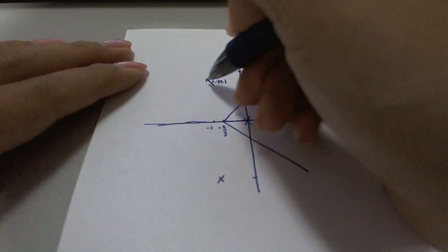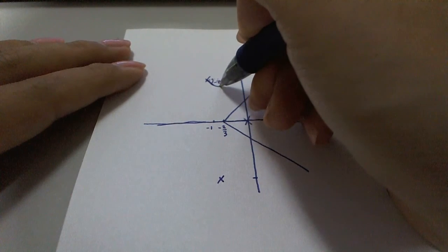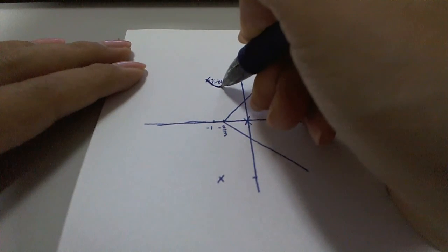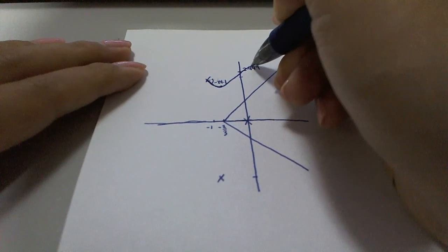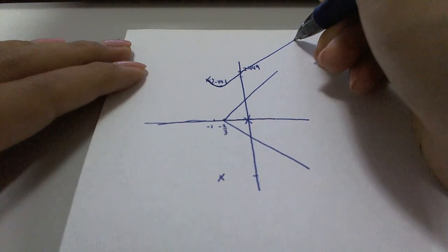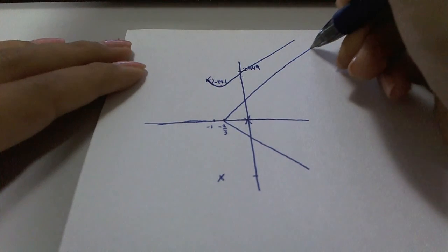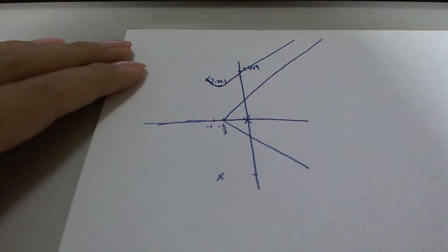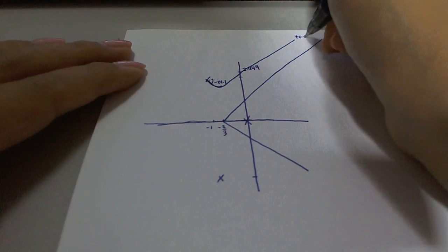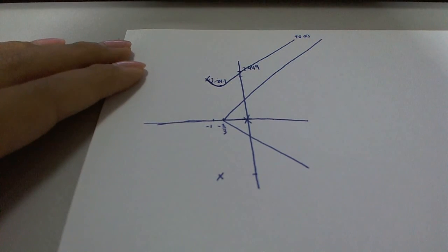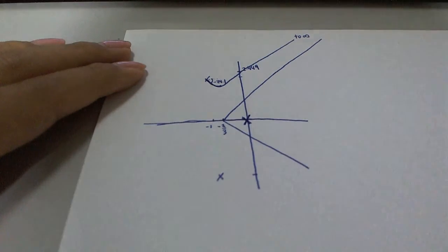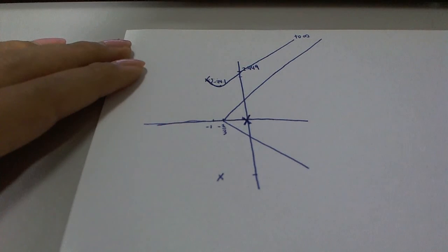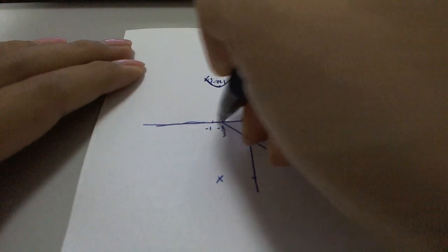The first one is from the first starting point, go down at minus 24.1, and then intersect the imaginary axis, and then it will go to infinity following the asymptote. And then the second one, we have this pole on the real axis, and in this case it will just go to infinity along the real axis.